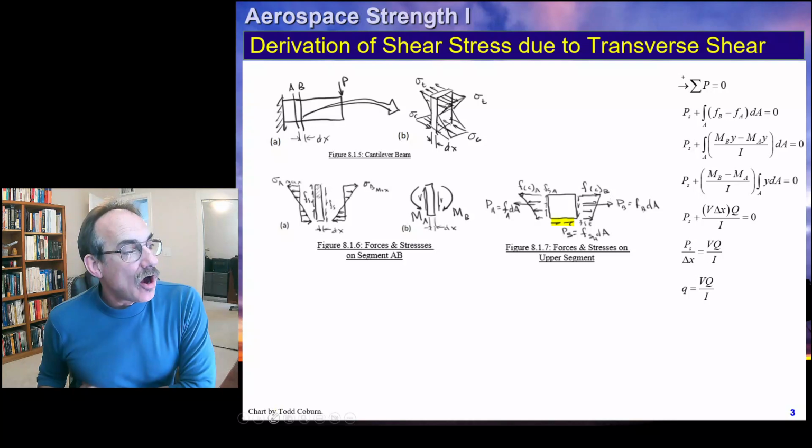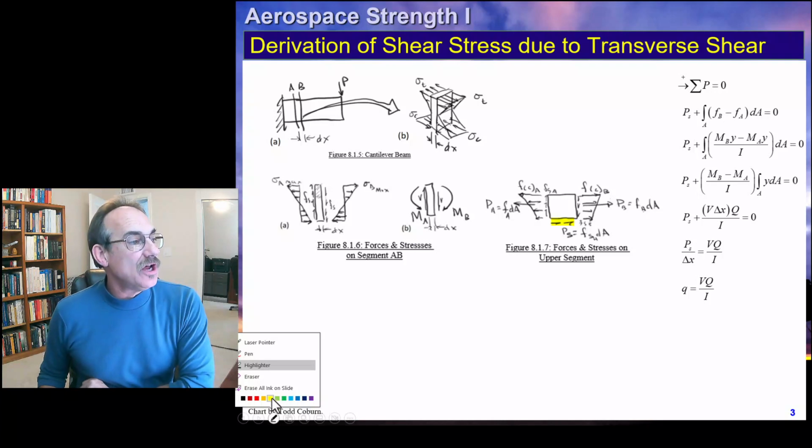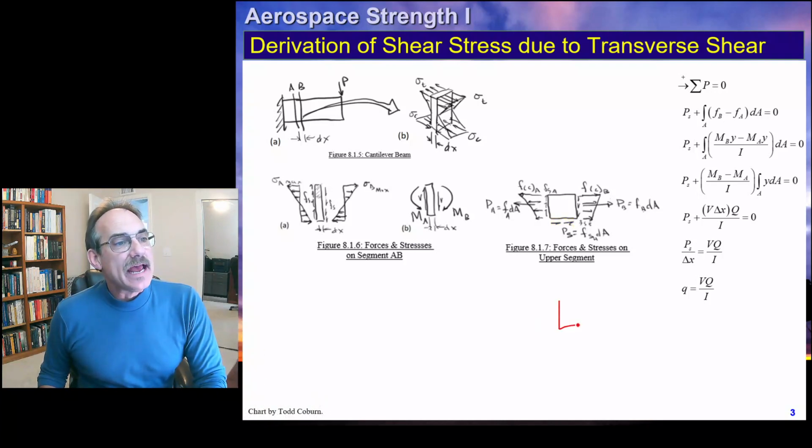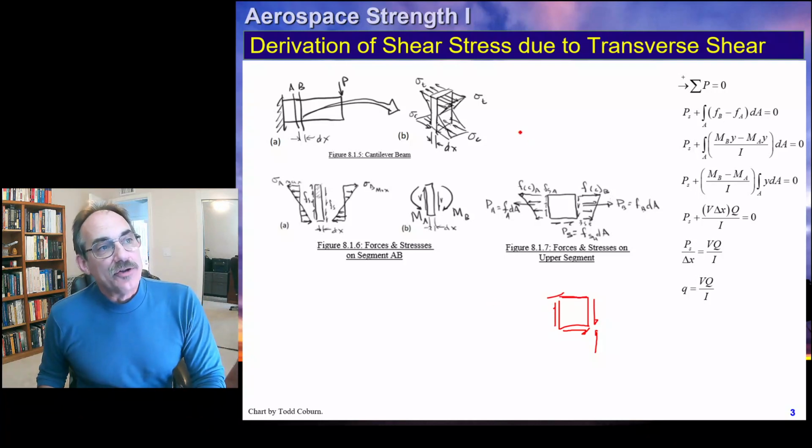Now remember, our shear elements, the romantic little dudes, are always mouth to mouth and toe to toe. What that means is, if we have a little shear element here with a shear flow acting that way, this shear flow is acting this way. That's our Q, right? And that means this is balanced, so this is upwards, and this is this way. Now you'll notice we have a cut here, so this shear flow, Q, can exist, but up here that's a free face, so there's no shear flow there.